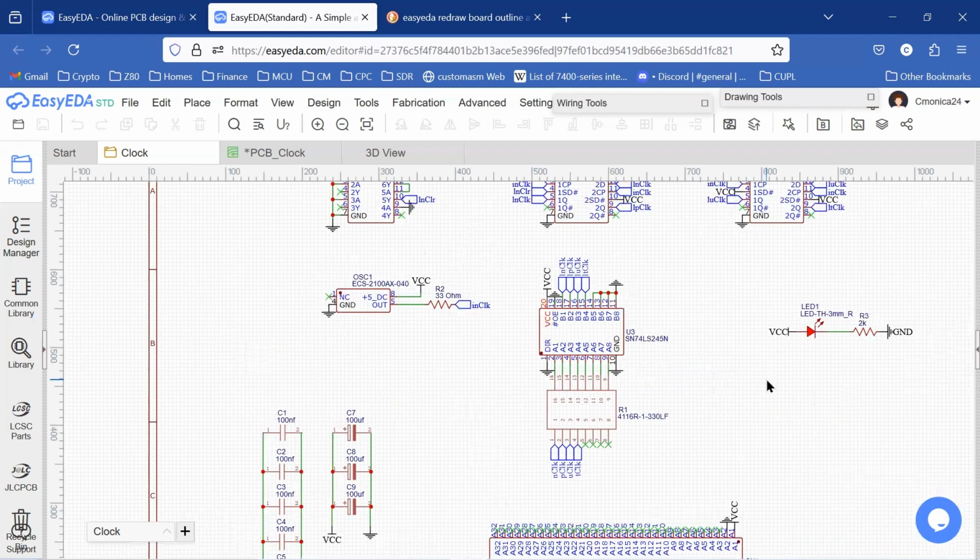Now, I'm also doing some other housekeeping things. We use these 33 ohm resistors mostly for everything that's driving the backplane. And those are for two reasons. Those are impedance matching resistors to help match the impedance of the tracks in the backplane. And the second function is that they help absorb signal reflections in the traces, and also going to the backplane.